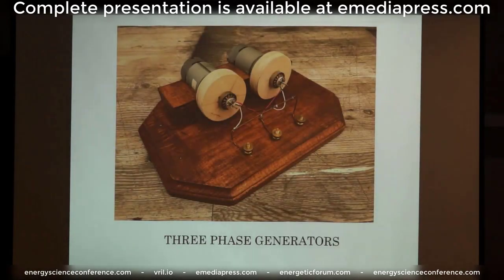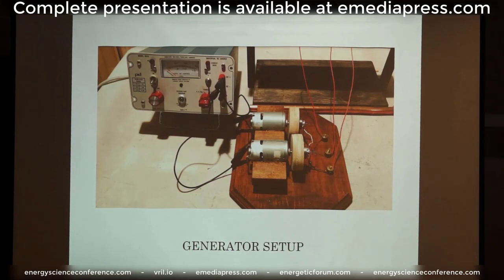Now I used these driven by 2 DC motors that would produce a combination of 3-phase. This was all mounted on a sturdy board so it doesn't vibrate and move, because it does vibrate like the Dickens and it starts moving across the table when I turn it on. And this is the overall setup. I have a DC source connected to the motors that spin these 3-phase generators, which produce enough power at 7.2 volts, about 11 milliamperes. And this gets fed into the transformers that are pictured up above right there.